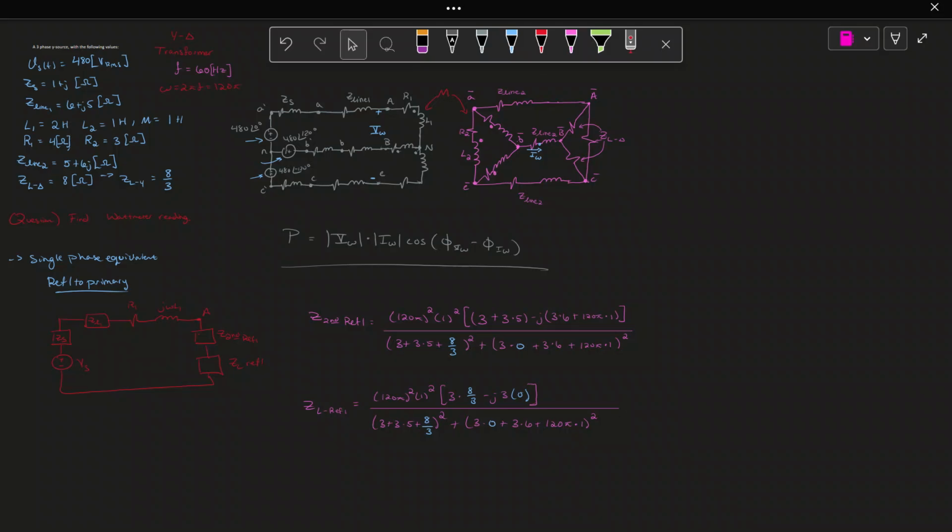This formula sheet gave a specific equation for Y to delta transformers. If it was a delta to delta transformer, this would be the exact same process, except you would choose the delta to delta equation, which we know is Y to Y. It's in the formula sheet. So you just look in the formula sheet, know how to use it, and know the impedances here and the impedances there need to be in Y configuration. In the middle, the transformers don't need to be. All you do is look at your formula sheet and fix it.